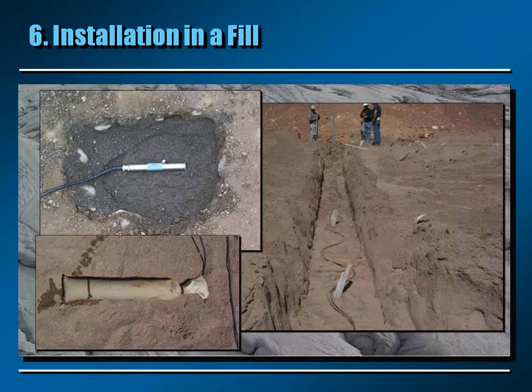On this slide here, you can see some pictures taken while doing the installation in an embankment. This installation is quite easy. You install the piezometer in a small trench.